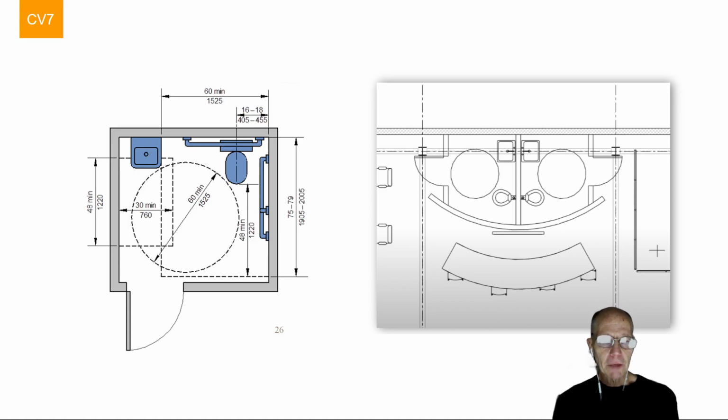And so bathrooms are specifically places of attention, especially when we think about considerations for wheelchairs. So in this image on the left, we have what is considered the ADA turning radius of 60 inches, the idea being that a wheelchair can pivot in that room without interfering or being obstructed with any of the fixtures that are within the bathroom. You'll also notice that with the toilet here, we're illustrating grab rails, which is a standard feature of an accessible bathroom. And then there's a whole host of clearances around these fixtures that are required.